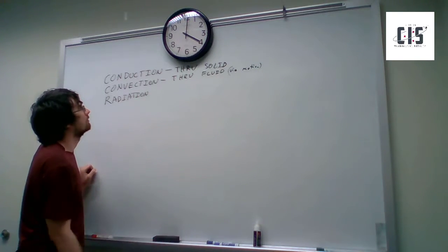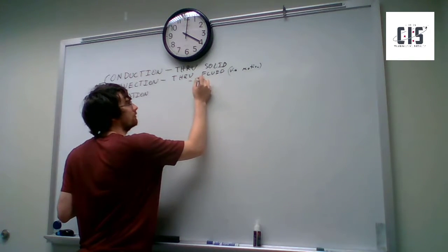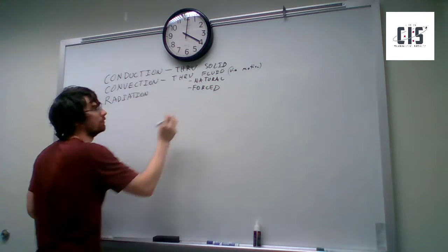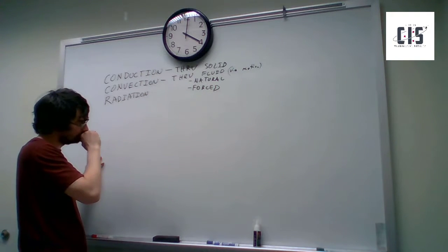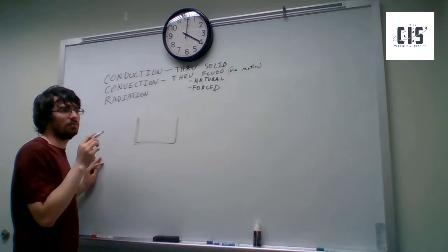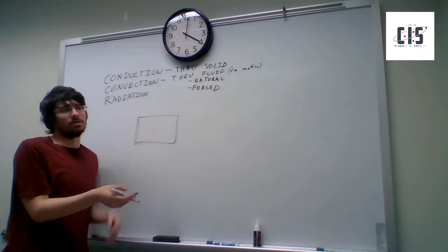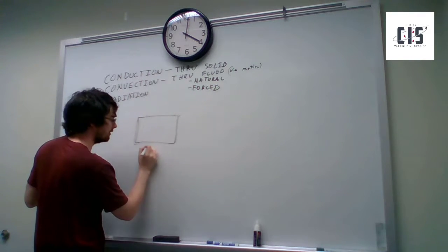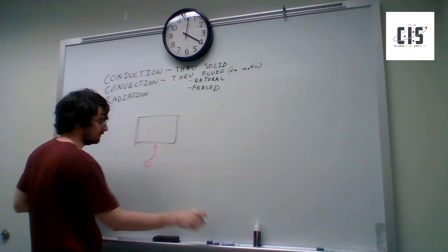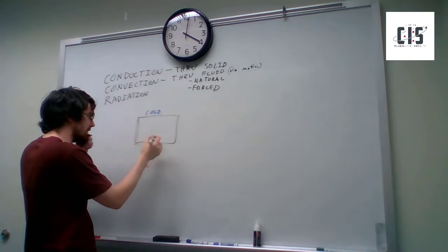Yeah, so conduction is pretty simple. Convection, there's two types of convection. There's natural and there's forced. So natural is what it is if there's nothing else moving the fluid. So the fluid isn't flowing already. There's no fan stirring it up or anything like that. In that case, if you have a hot surface and then a cold surface, in gravity at least, heat tends to rise.